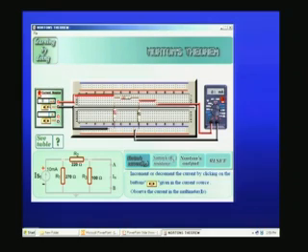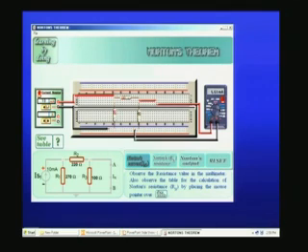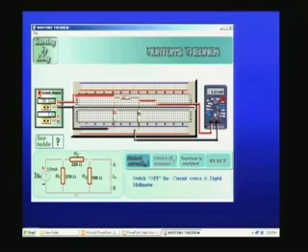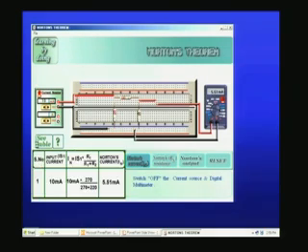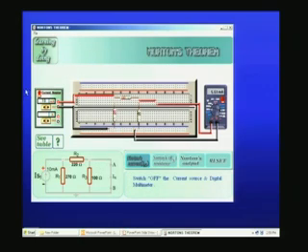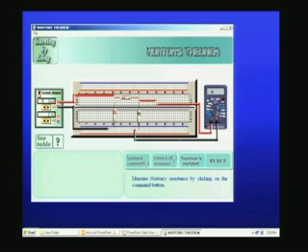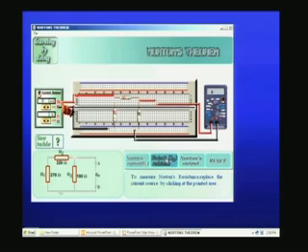Now increase the current to 10 milliampere, because that is the current value IS1. Now I have 10 milliampere current, and you can see the short circuit current is 5.51 as measured by the multimeter. If you want to look at the calculation that is shown here, IN is IS1 star R1 by R1 plus R2, which is 5.51, we already calculated. So we have obtained the Norton's equivalent current source.